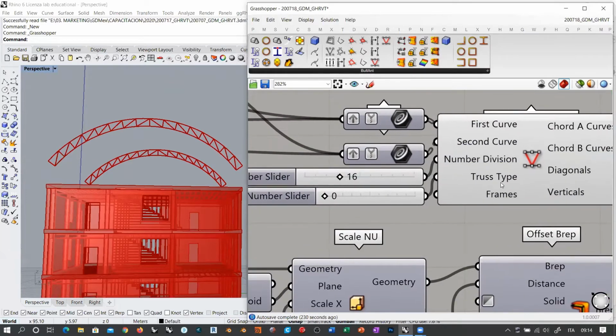And truss type. There are only, well, only is not exactly a proper term because this is one of the most complete truss creators. So you see that there are 6 types of truss structures that you can create. Now the default is the Pratt structure, but you can see this is actually changing the way that the diagonal and vertical elements are created along the truss. So there are symmetrical and asymmetrical beams. In this case, for example, for us, it is important to pick some symmetrical structure. So just the usual schemes.